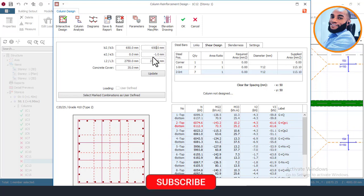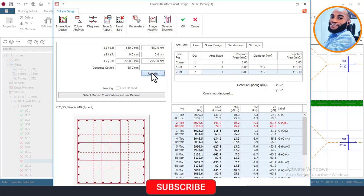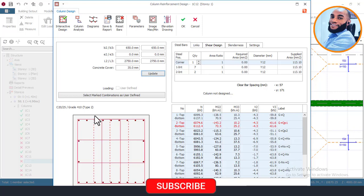And I'll come here, let me just remove this to minor and make it 0, sorry, 0, and I'll come here and say update. Okay, now once I click on update, I will now come here and then click on reset bars. Okay, so by clicking on update now, you can see the size of the column has changed.